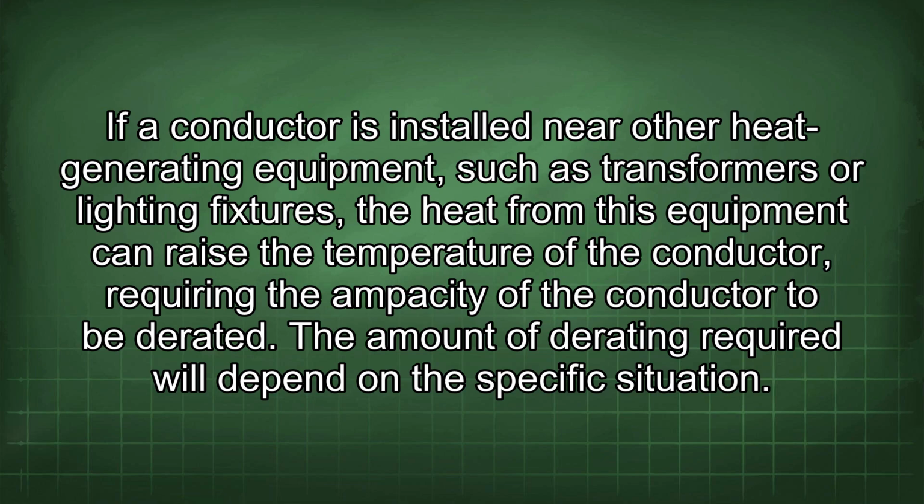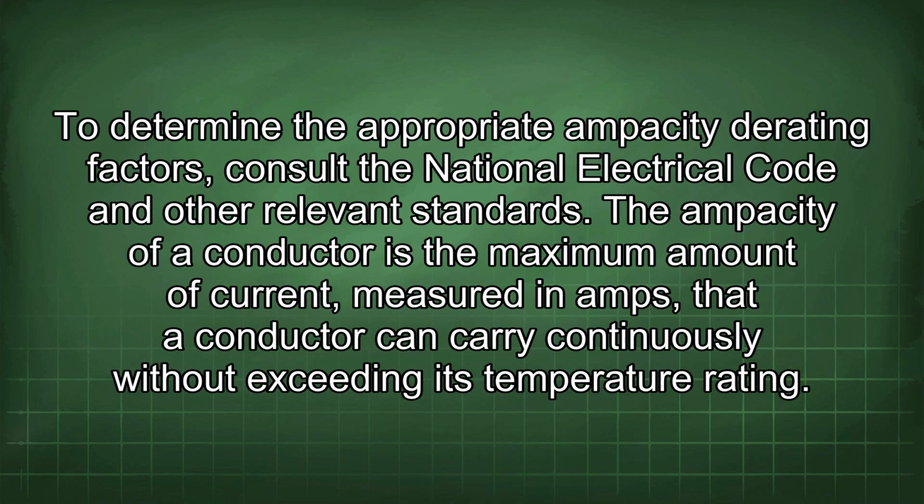Thirdly, presence of other heat-generating equipment. If a conductor is installed near other heat-generating equipment, such as transformers or lighting fixtures, the heat from this equipment can raise the temperature of the conductor, requiring the ampacity of the conductor to be derated. The amount of derating required will depend on the specific situation. To determine the appropriate ampacity derating factors, consult the National Electrical Code and other relevant standards.